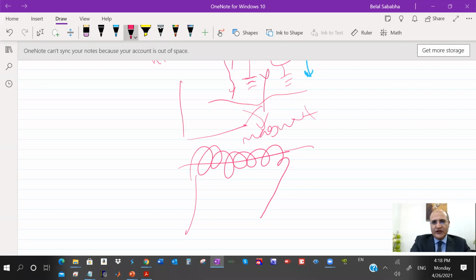And this would be a circuit for, I don't know, a motor or whatever with its own power source, and you use this magnet. If you write a 1, and this is the ground, this is port B0, you write a 1 here, then you cause a magnetic field to be created, and the switch to be closed, and thus close the circuit to turn on the motor.